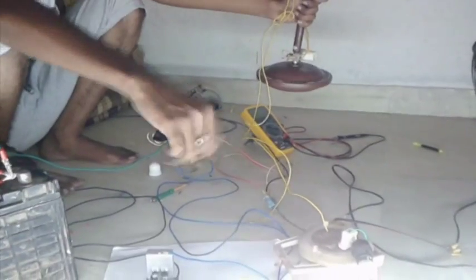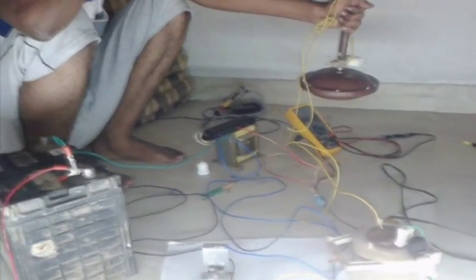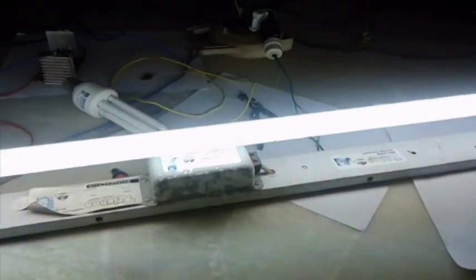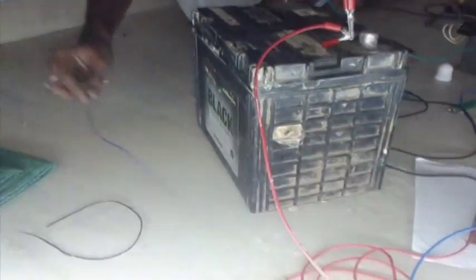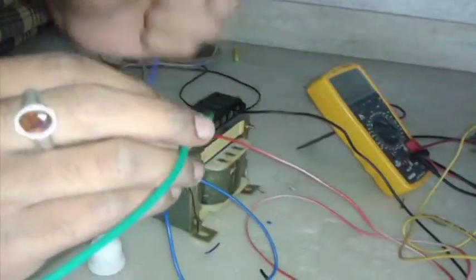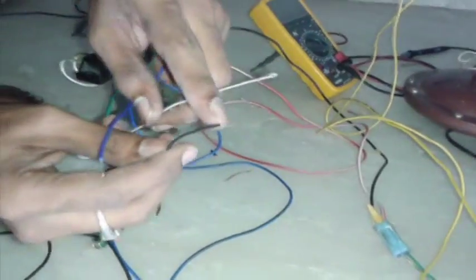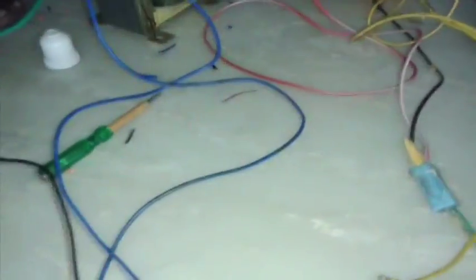Why I want to tell you this is that initially we tried to glow the tube light and run the fan, but we could not make it. Initially the tube light was just blinking, but not glowing. But now why is it able to glow? Because initially we used these kinds of wires to connect everything. Instead of this 1.5 square mm wire, this is a very small wire and it's a single lead wire. This is a single lead wire and this is a multi-lead wire.